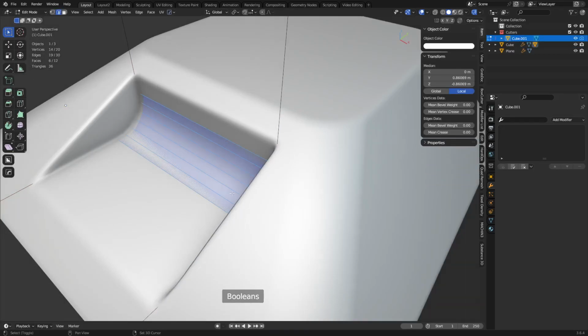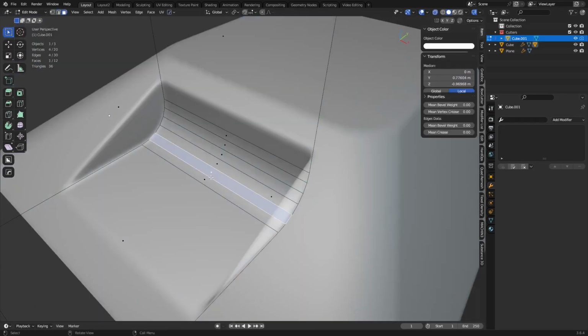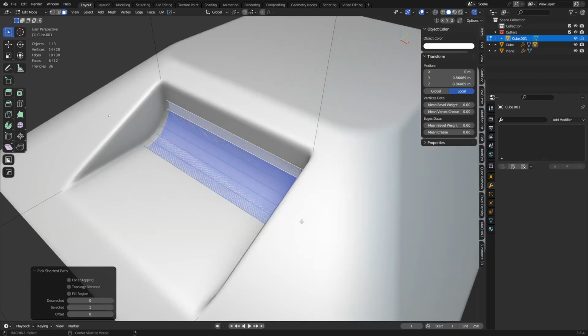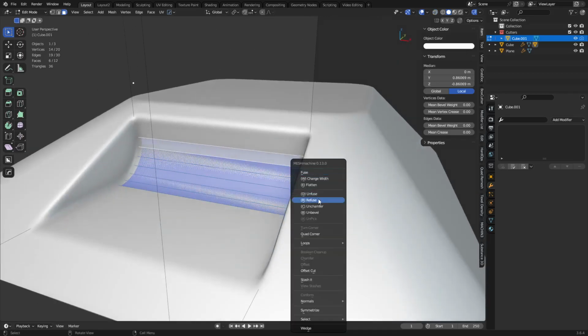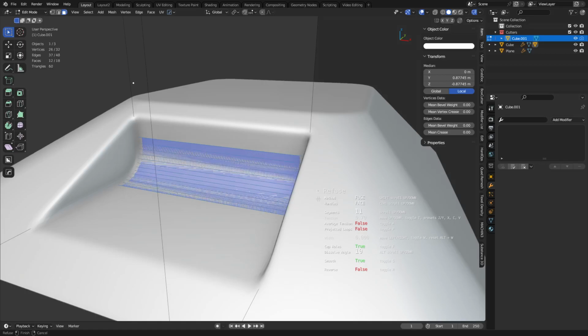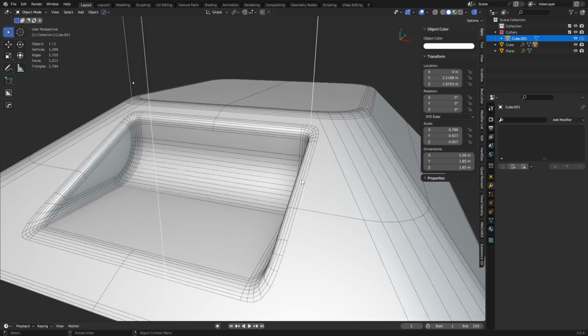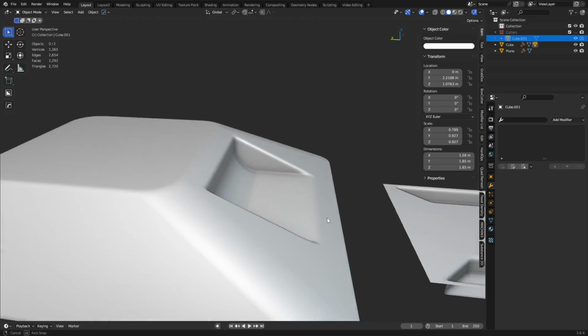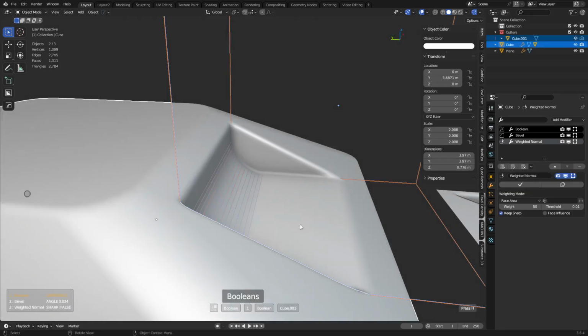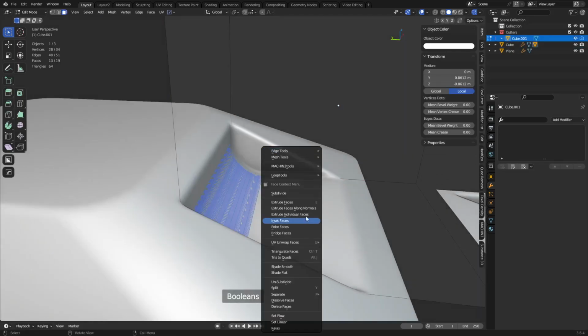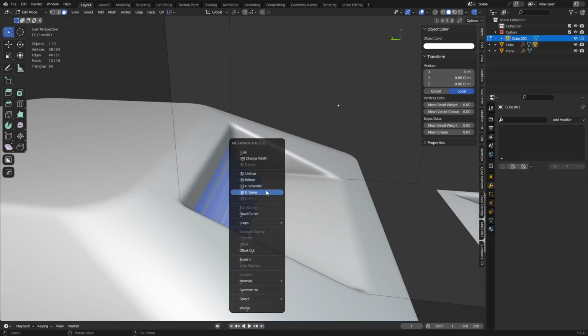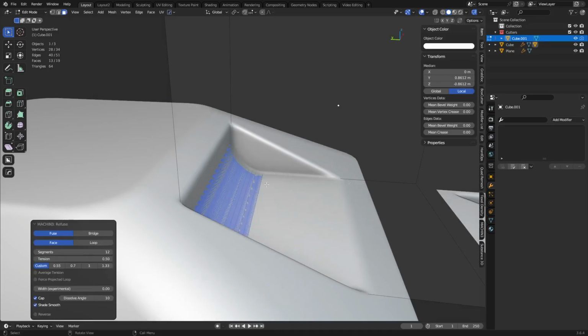If you ever mess up on something like this and you're doing destructive modeling, get Mesh Machine for this specific purpose right here. You can use the refuse feature and you can do this all day long. You'll see you can even change the tension amounts. So we can turn it back to 0.5 if we don't want to use 0.7 perhaps. 0.7 creates a better bevel usually, in my opinion. It usually looks cleaner is what I'm saying. But if you wanted to refuse and do 0.7 instead, you can change these things.